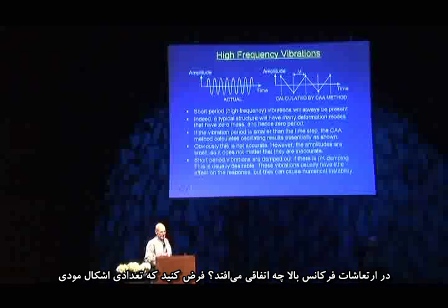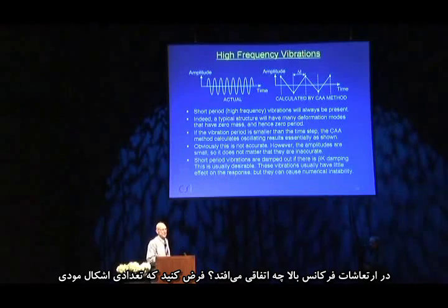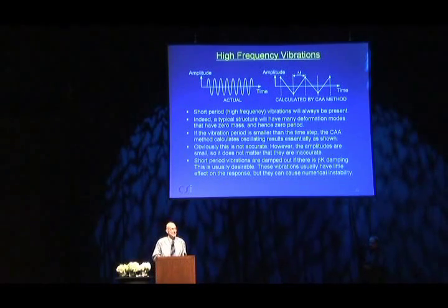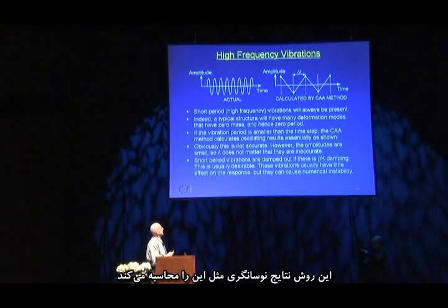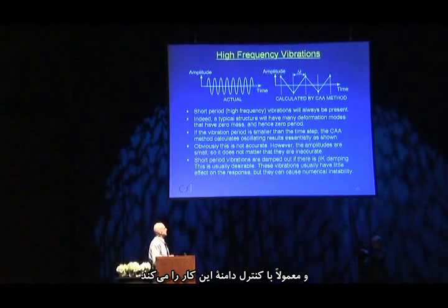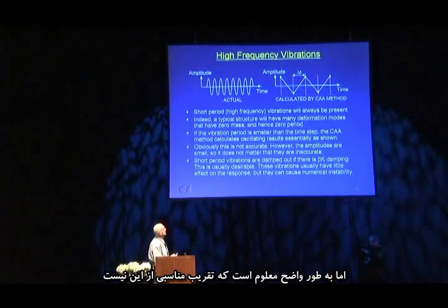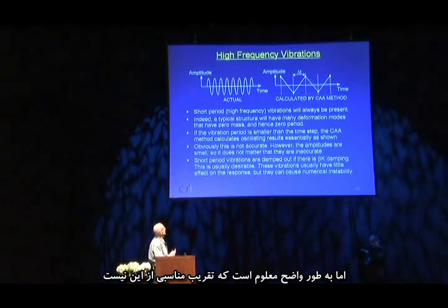What this indicates here, suppose this is some mode shape which has a very short period, and it might be vibrating in this short period, which may be shorter than the time step. The method still works. It'll still calculate a result, but it'll just calculate an oscillating set of results like this. And usually with a controlled amplitude, the amplitude is often not too different than the proper one, but clearly this is not a very good approximation to this.